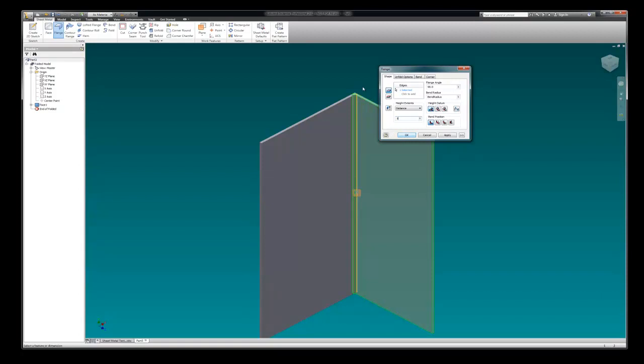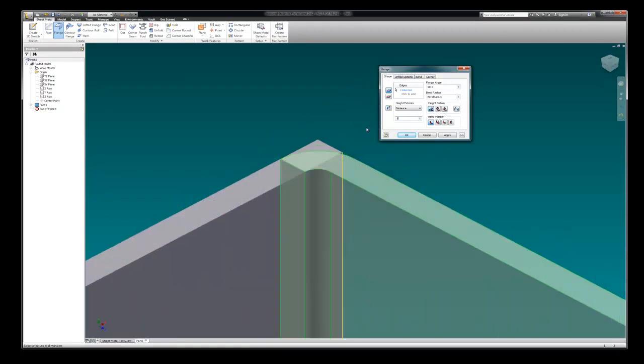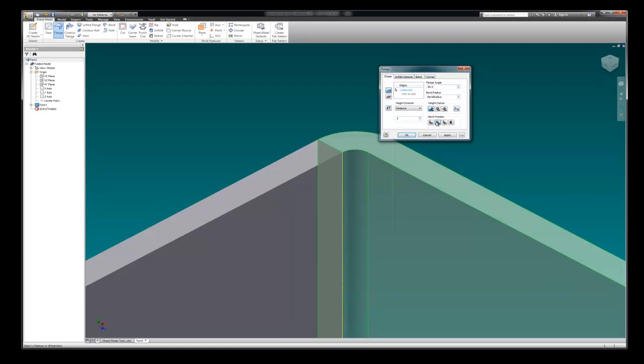Now here's the interesting thing. I'm going to zoom in here really close, and I want you to watch right here in the corner as I move these bend positions around. So right now it is from the other corner to this outside corner here, and this outside is 6 inches. When I go now, look what happens. It moves the bend to the outside, so that panel would become like 6 1/4.